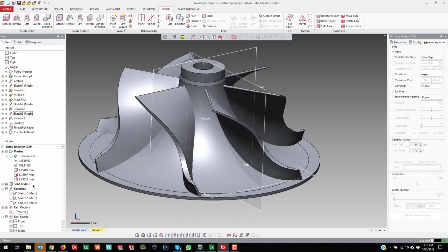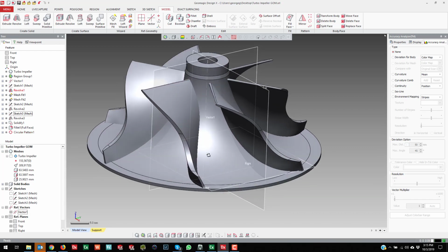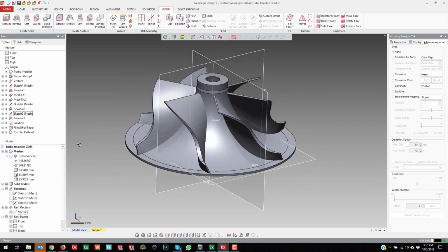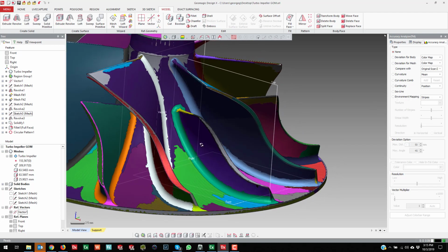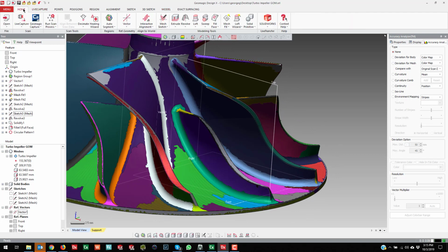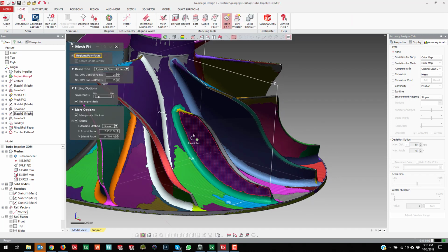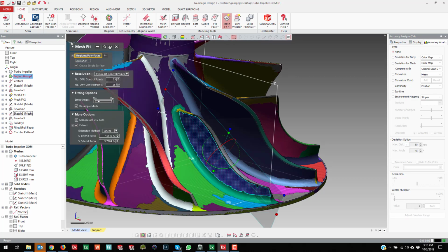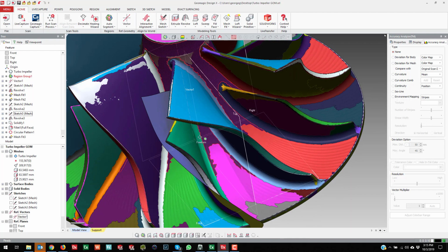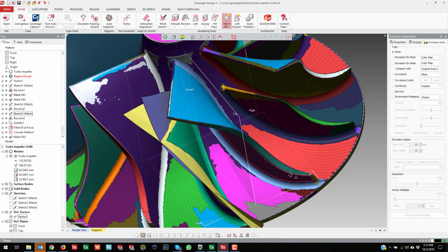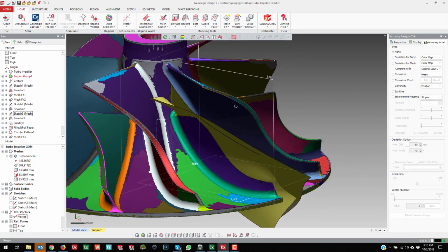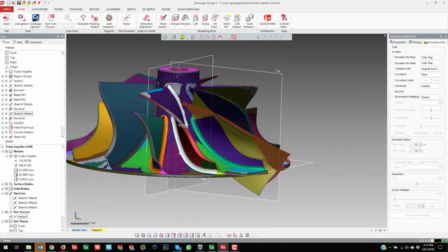All right, now for the other side. All I really need to do, modeling wise, is fit these two sides as a mesh fit again. Everything else is ready to go. So if I go to mesh sketch, I will leave that same setting, hit OK. Mesh sketch again. OK. Now, remember the inner and the outer.